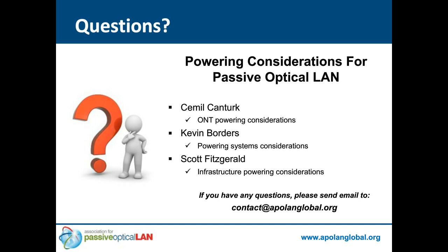The other thing about digital power is the jury's out on how you comply with the National Electrical Code on that, because the voltage is significantly higher than 60 volts. So do you have to put it in a conduit? There's some debate about that. If you do, obviously that's going to blow your cost model up.